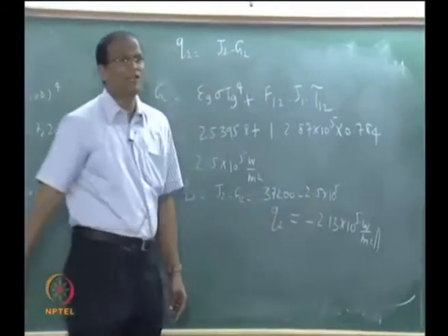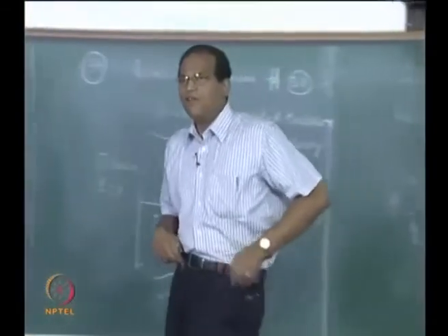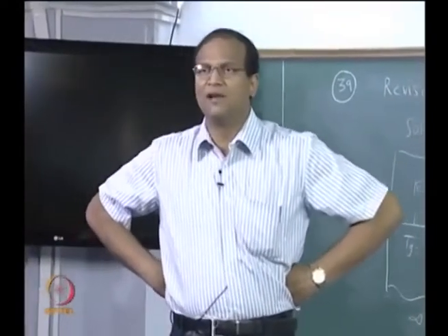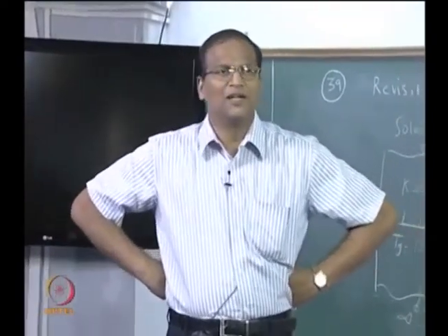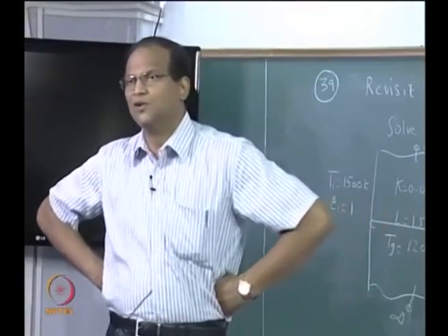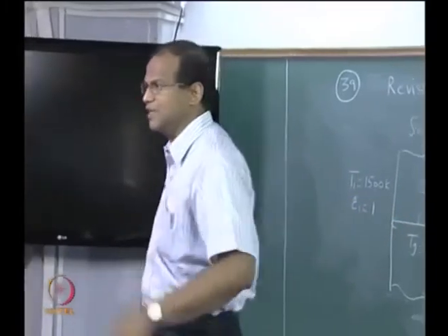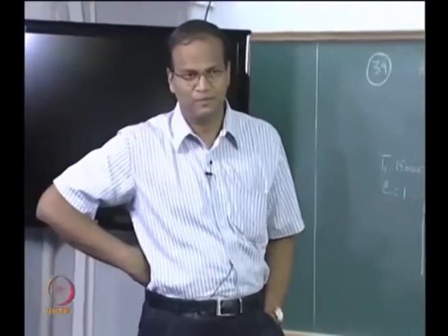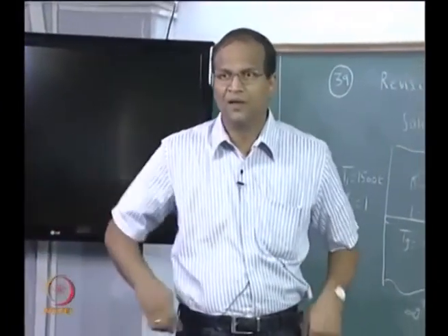So, if you are given a black enclosure or a problem involving two black surfaces, parallel plate formula, you can either use the analytical method, I mean get the solution, use the solution, get the exponential integral, or you can use the theory of evacuated enclosures to solve the problem. Okay.